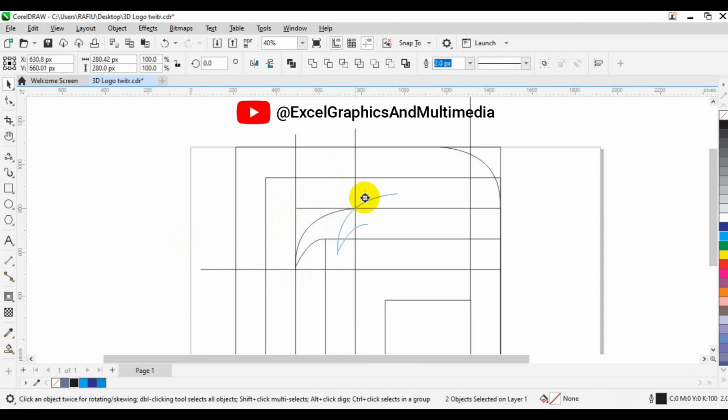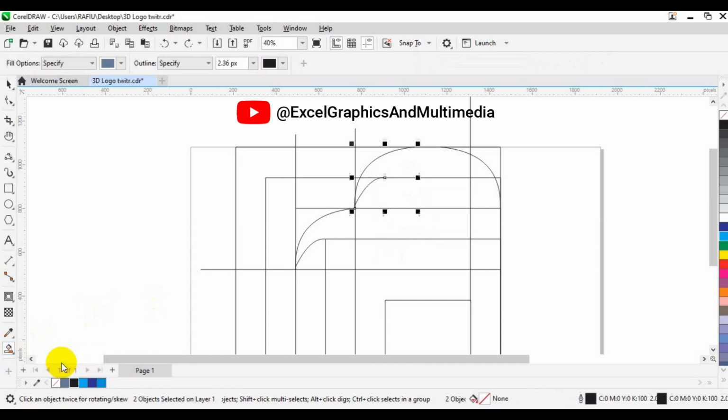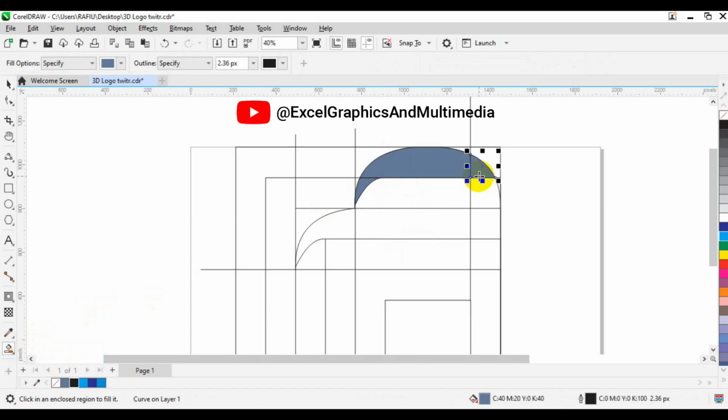And right click, then make sure you drag it to the top right here and snap to the edge at the top. Then click on copy here. Next thing you need to do is to come down below here, click and hold down and choose your smart fill. So having chosen your smart fill, you can fill some necessary points like this.